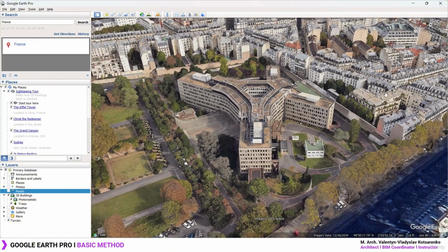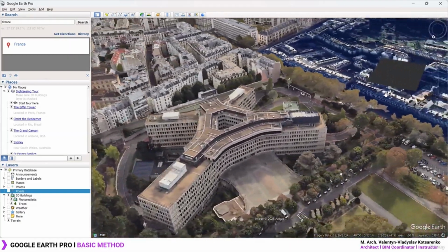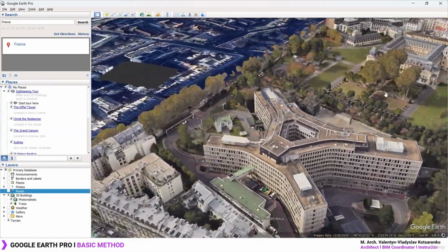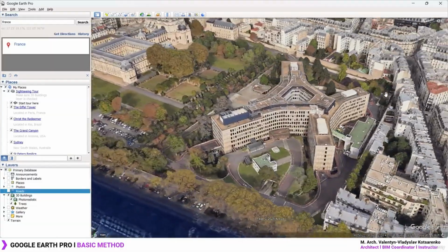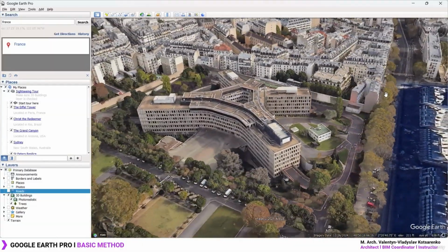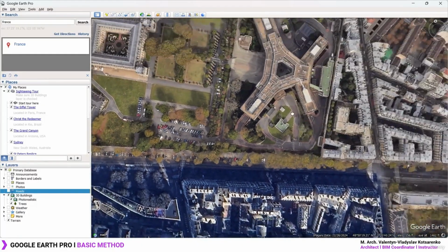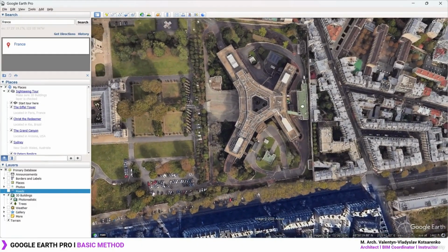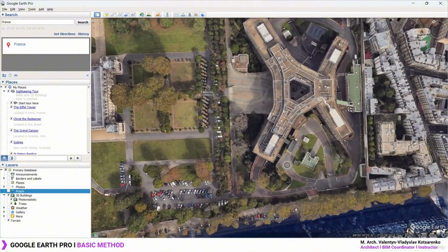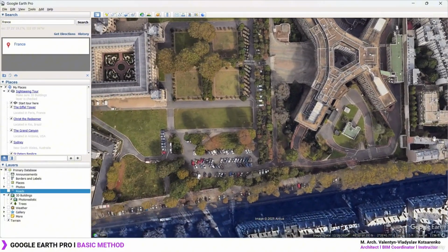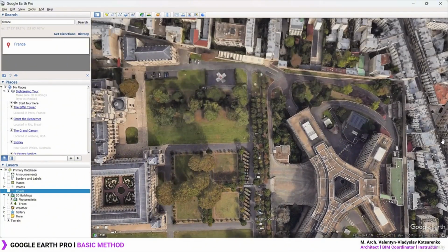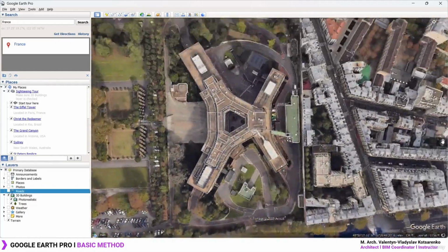Now, the second way would also be possible if, for example, you create an orbital fly-through. You simply orbit around the building in this manner. You take a bunch of photos, and in this manner you can also generate your model, and it's going to work perfectly. In this case, what I believe is the best manner would be to combine both methods. You create a fly-through following the zigzag movement, something like this.